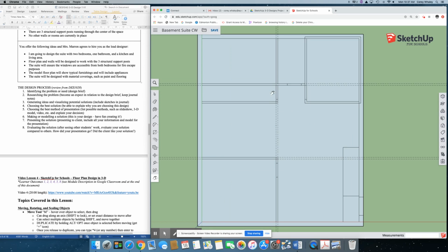Okay, so I figured it out. It's going to be about every 9 feet. That's where I need to have a post. So I'll just grab my tape measure tool and we'll just drop some guides down just for ease. So I'm going to go right from the interior of that wall and we'll go to 9 feet or so. Let's see what that looks like. So 9 feet, where is that going to place us? Right in the middle of that door. So for this one, we know our post is actually going to be right in that inside area.